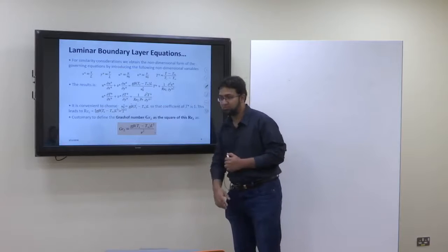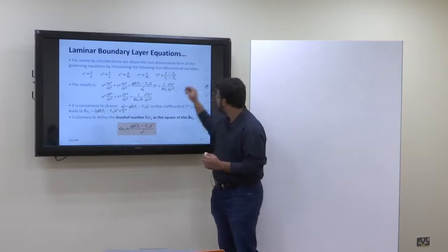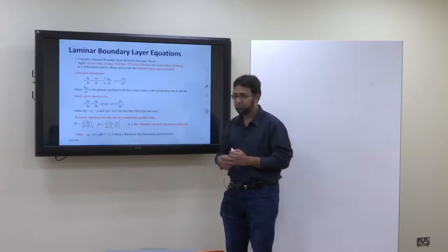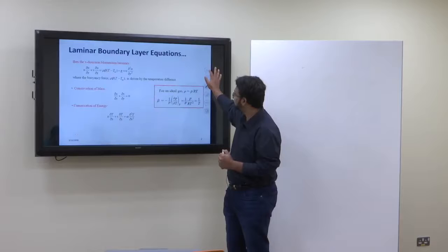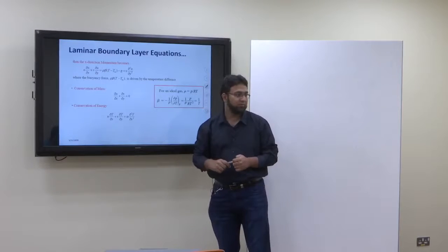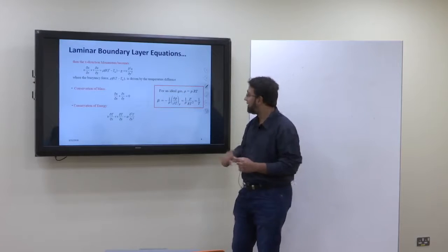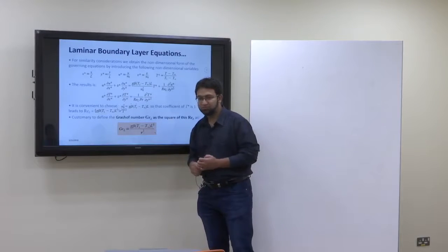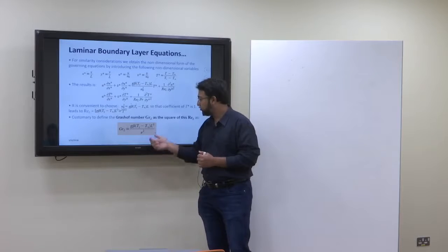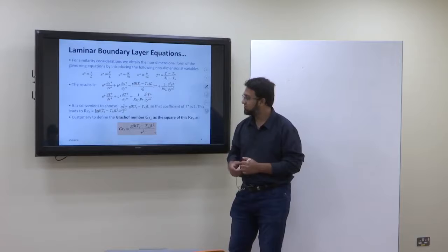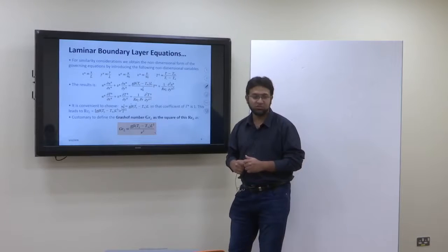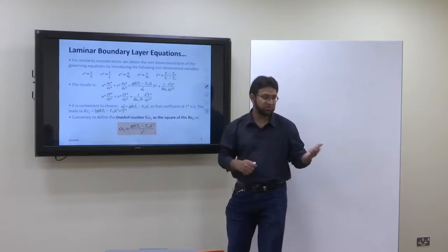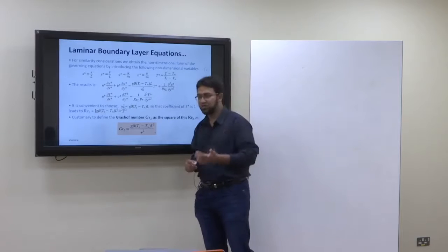The Grashof number has a formula, and we discussed it. Here beta is the volumetric thermal expansion coefficient, and in the end it comes out to be just the reciprocal of the mean film temperature in Kelvin. So we have g beta (Ts minus T infinity) L cubed by mu squared. This is the formula for the Grashof number, which is used in free convection. The Reynolds number was for forced convection; for free convection, we use the Grashof number.